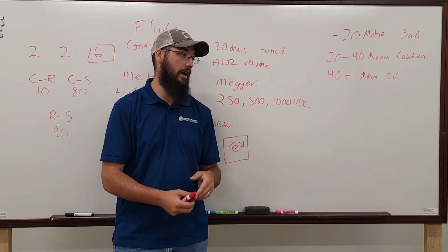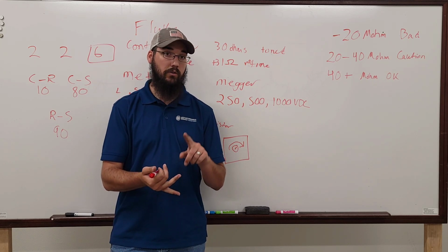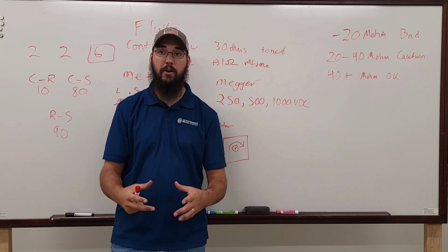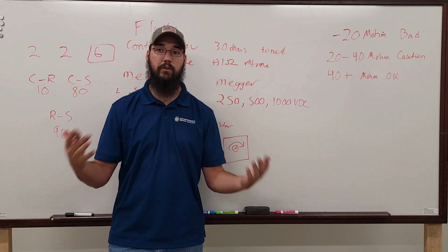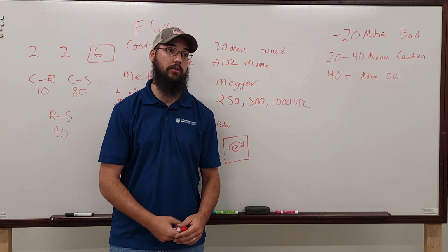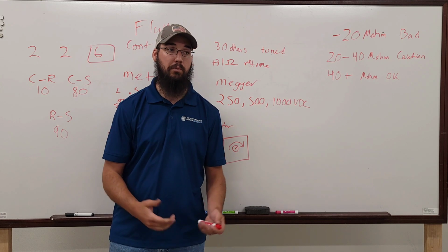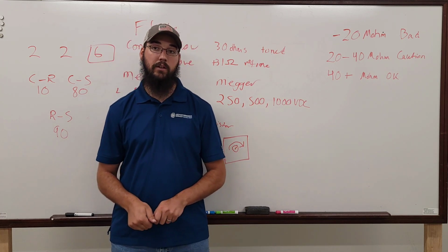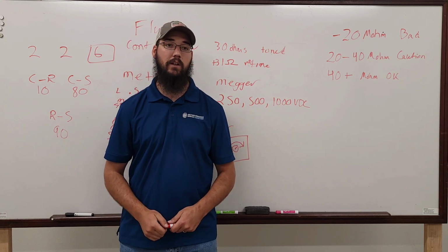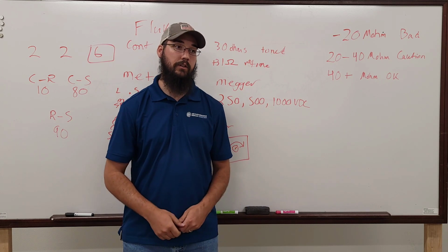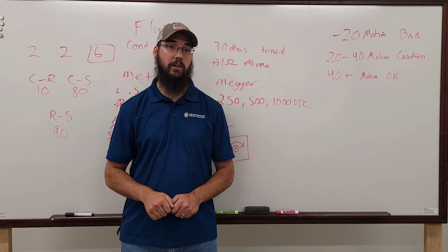Just right there, it's very likely either an alignment, whether it be a pump or blower, or motor isolation, whether the mounting itself, what it's bolted to, and whatever springs, whatever it has. You know, those springs on those air handlers, they do break. They will break and they'll get all lopsided, and that's part of many of our inspections. Technically, that is part of the scope. You're supposed to look down in there and see what that spring looks like, see if it's sitting on its side. If we catch that, that's a motor killer. That spring, as insignificant as it may seem, that's a motor killer.